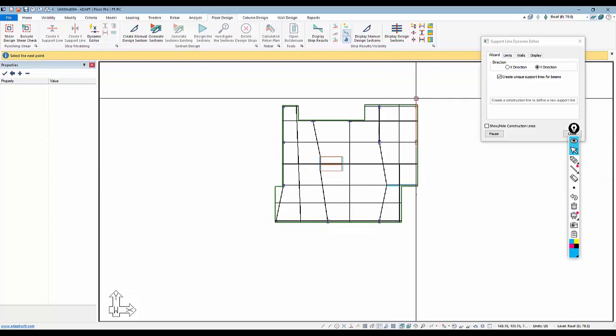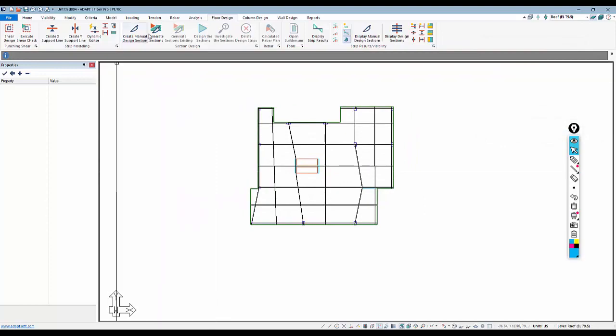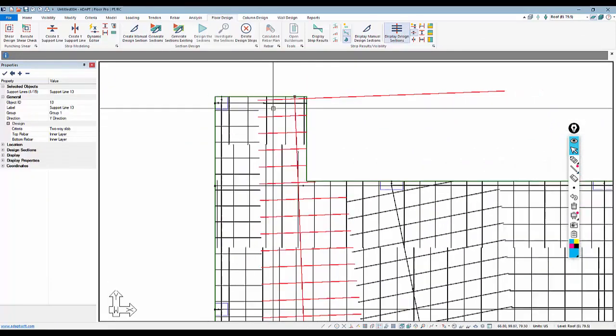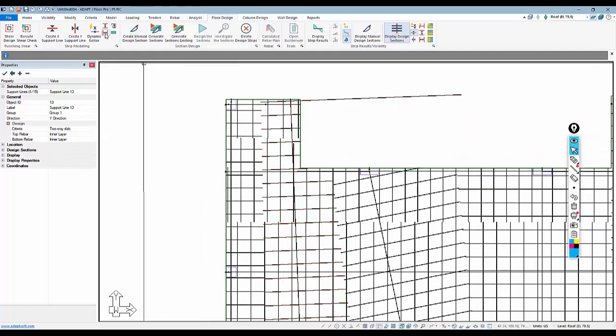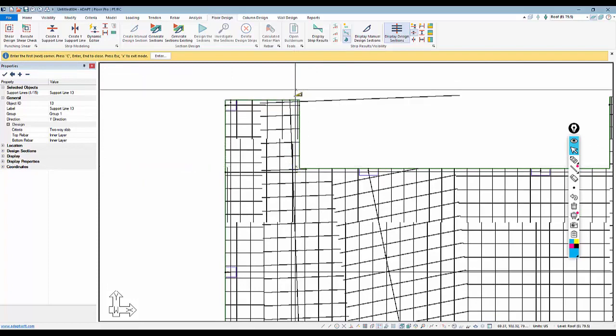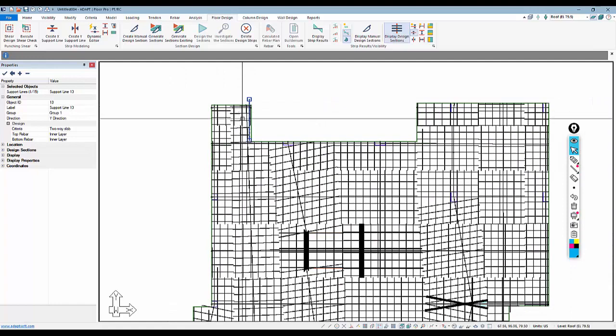Column strip on the outside. So something quick like that to generate the strips. I can go ahead and generate those. This cut is occurring outside of the slab, so if we add a Y direction splitter here, let's see if that cuts that off. Okay, so that just bounds that tributary to that line.